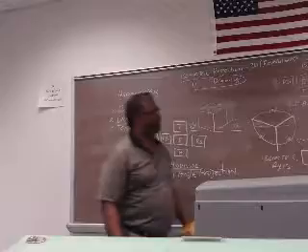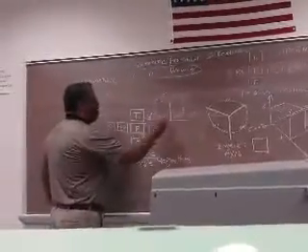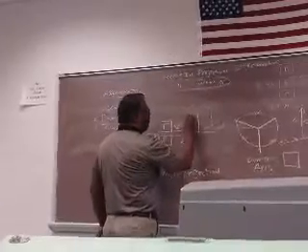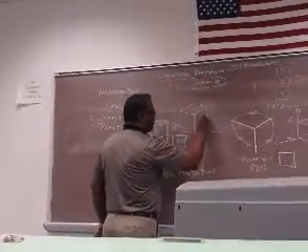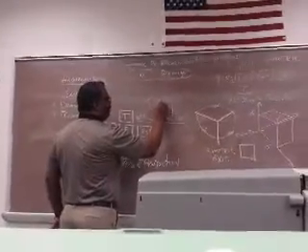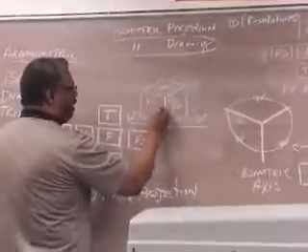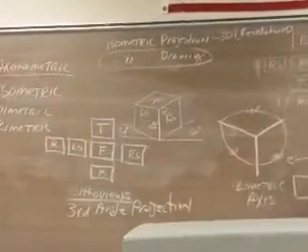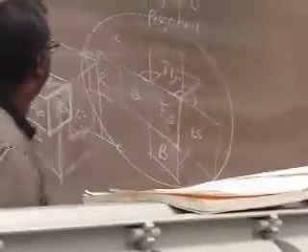So that's your isometric. Well, your isometric has orthographic views associated with it. So we're looking at the front, right side, of course the left side is back there, top, the rear is back there, and the bottom is right there. So when we take this isometric that we see, and we're looking along the orthographic views, we get this arrangement of views.